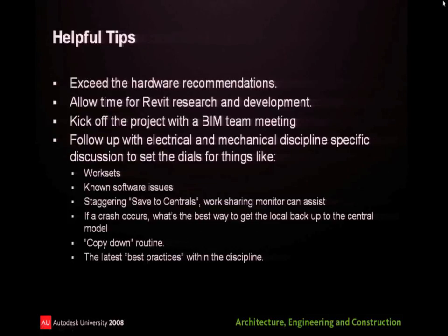They can open detach from central, with all work sets available. They can specify a work set on a heavier model, so they're only opening one work set or two instead of the entire model. Even our electrical folks, we put in a little button there, they could open their electrical model with Revit architecture.